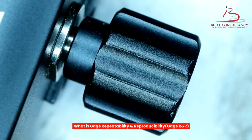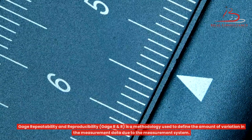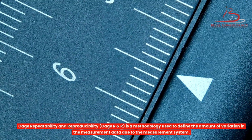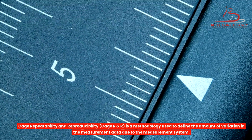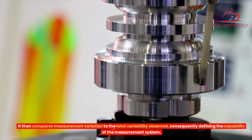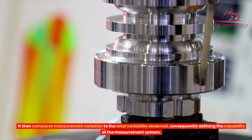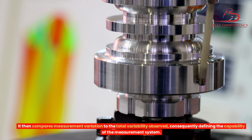What is gauge repeatability and reproducibility, GageRnR? GageRnR is a methodology used to define the amount of variation in the measurement data due to the measurement system. It then compares measurement variation to the total variability observed, consequently defining the capability of the measurement system.